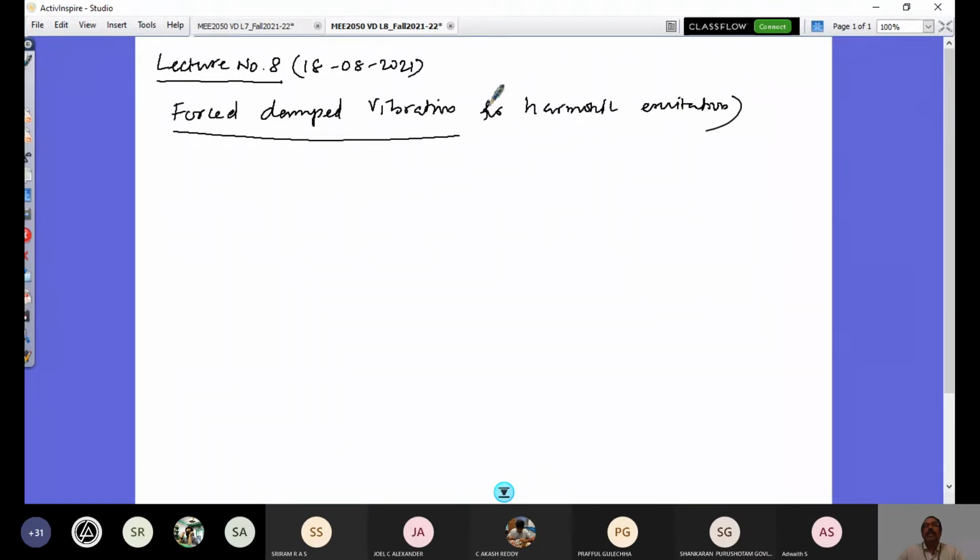That means you can also have other excitation function and you can look at the response. So the excitation function can be deterministic like this case, or it can also be random case. For an example, the excitation that comes to the tire and road interaction of our vehicle in our course we are going to study is not harmonic excitation purely. It is random excitation. So there are methodologies to account the random excitation and the vibration response. That is what we will be learning in our vehicle dynamics course in vertical dynamics part. Make a note of this point.